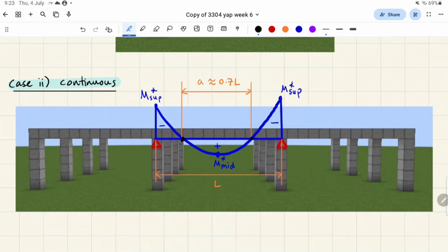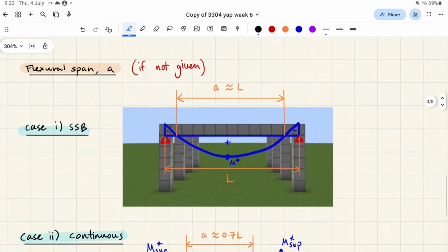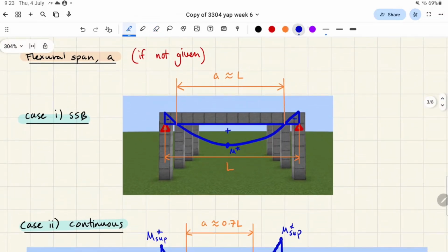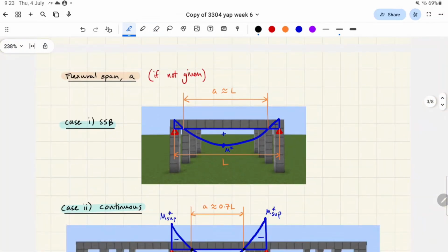That's the part which is in positive bending. Do you know what I mean? And for a simply supported beam with rigid connections like this column, this is approximately equal to just the regular span. Cool. So anyway, I think you guys get it just from the visualization.